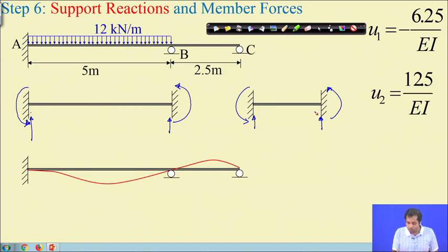Just now I mentioned this is for the kinematically determinate structure. There are no degrees of freedom, all degrees of freedom are constrained. Now, in addition, when the structure deforms, because of the deformation there will be some actions at the joints, at the supports, and suppose these actions are this, and similarly these actions are this. So the total support reactions at any joint will be this plus this.